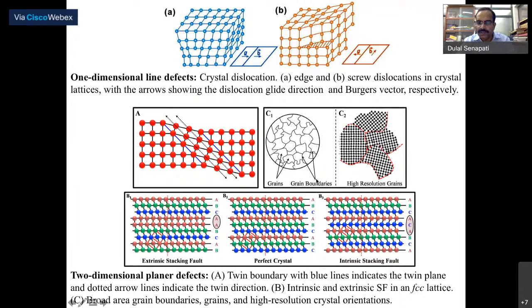Or it could be like a grain boundary. So if in a nanomaterial there are several nucleation zones, and all are simultaneously growing and then finally connecting to each other, making a nanoparticle, it can give a grain boundary enriched defective nanomaterial. So you can see that this is one grain, and the pattern of the crystallization is different from another grain. These we call grain boundary defective nanomaterials.